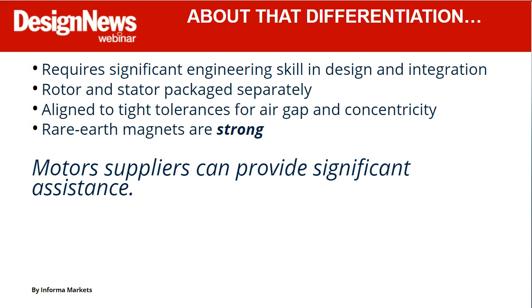You need to know what you're doing. Rare earth magnets in motors are really strong, and people can get hurt. So, you have to understand what you're doing. You've got to have the handling fixtures. But talk to your vendors, because that's what these folks do. So they can work with you and help you specify and pull everything together.